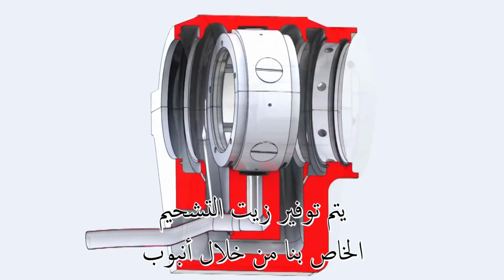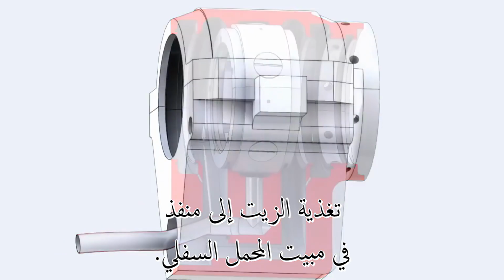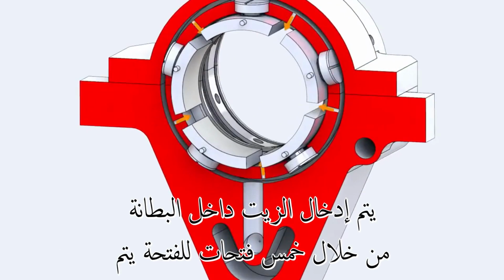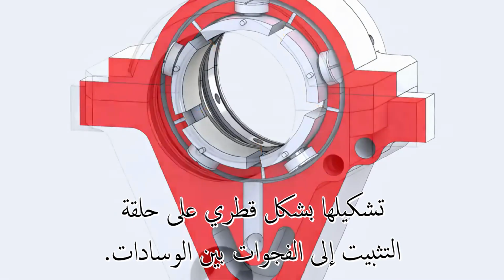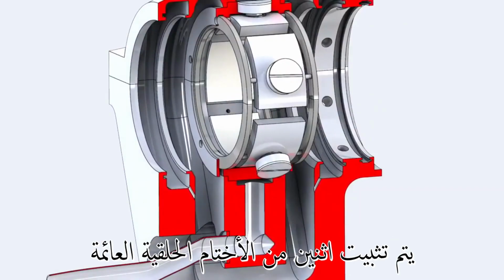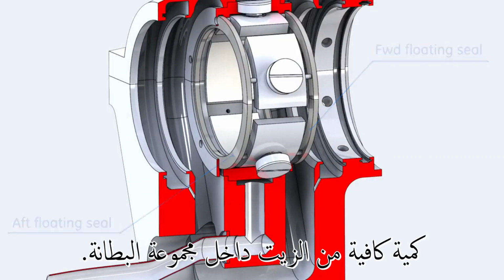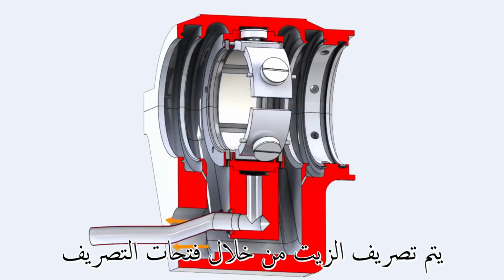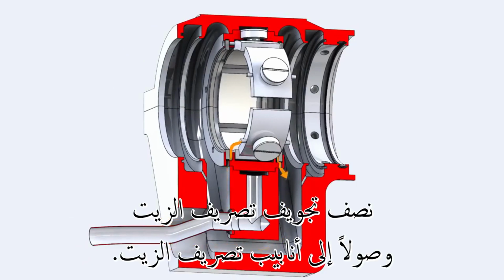For lubrication, oil is supplied through the oil feed pipe to a port in the lower bearing housing, where oil fills an annular space around the liner retaining ring. Oil is admitted inside the liner through 5 orifice holes, machined radially on the retainer ring to the gaps between pads. 2 floating ring seals are mounted on both ends of the retainer ring to maintain an adequate amount of oil inside the liner assembly. Oil is drained through the vertical drain slots at the bottom of the lower retainer ring half to the oil drain cavity down to the oil drain piping.